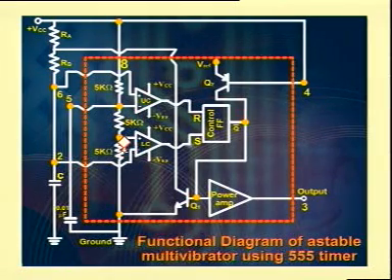volts. Then due to this positive voltage, first of all the initial condition of the 555 timer as astable mode is that in the discharging path, instead of reaching up to 5 volts, when it reaches 6 volts, then itself it changes state, because now the lower comparator reference voltage is 6 volts.